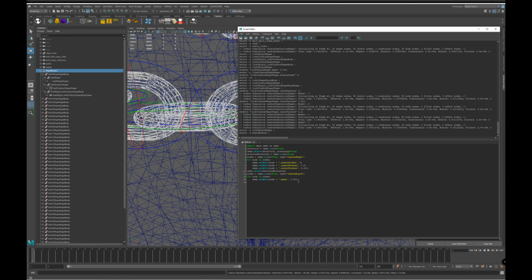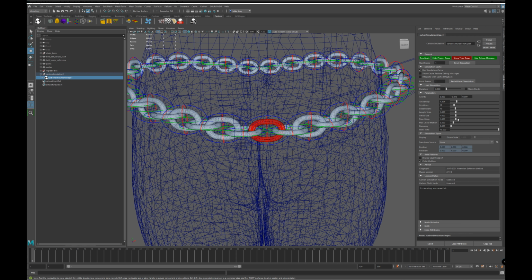Next we are going to set up the simulation parameters. We want our scene scale in centimeters, so that's 0.01 meters. And we'll still need a reasonable number of subdivisions, as the chain is going to drop on the loops. So let's go with 30 subdivisions. We are also going to need some lead simulation, and we'll come back to that a little bit later.